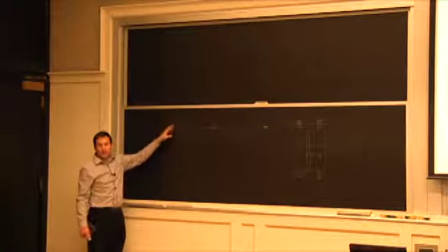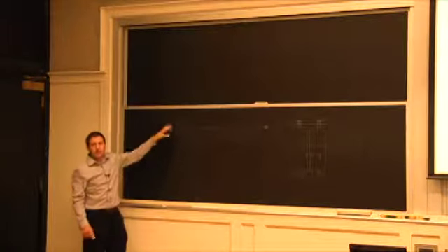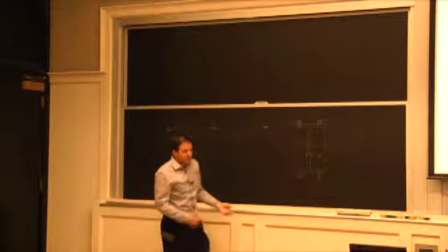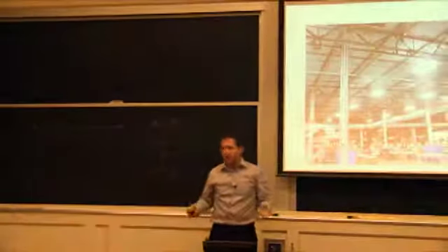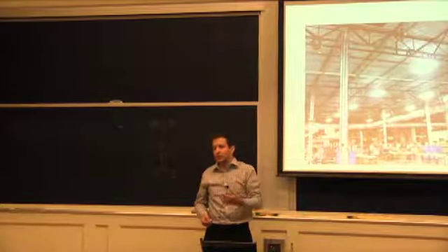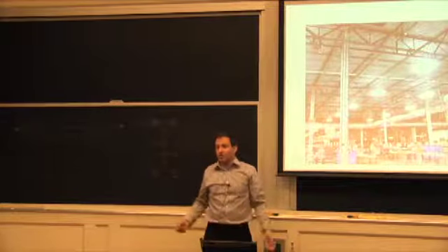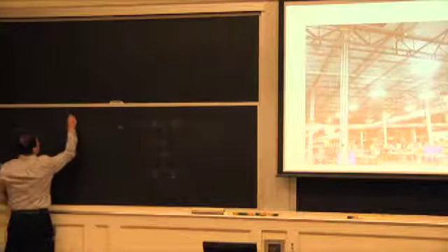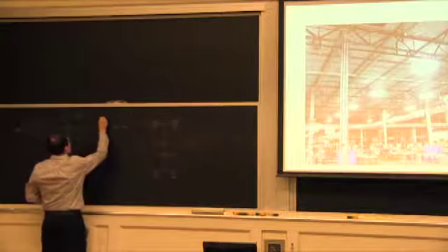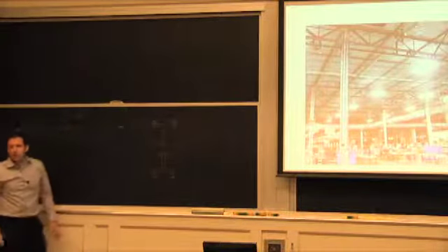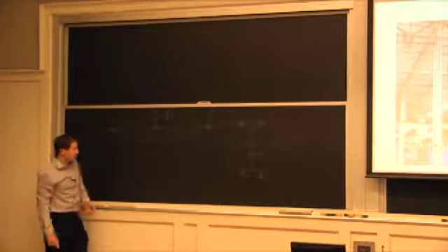If you're going to pile up more snow, because now you have two elevations, you have to worry about whether you're close to the edge or in the middle. If you have a big mechanical system like a big air conditioning unit, that would also create some snow drift, and there are rules for all of it. So when we're talking about, say we're going to call this the demand here, it's very prescriptive. You can go to the code and it tells you the load per square foot overall that you're putting on and that you have to design for.